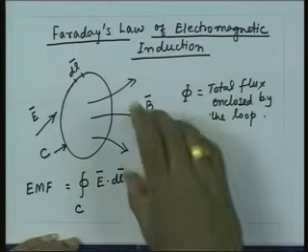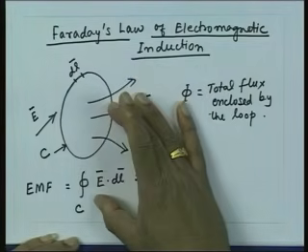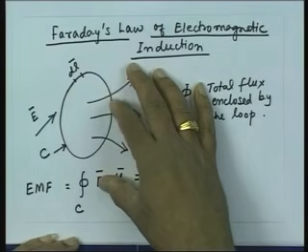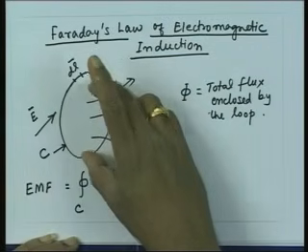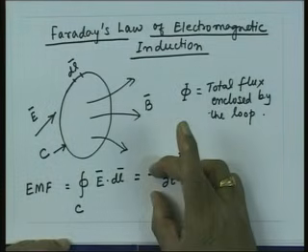What that means is whenever the magnetic field tries to induce the EMF in the loop and the current flows, the magnetic field produced by that current tries to oppose this. So, this phenomenon cannot go on increasing indefinitely. So, the magnetic field produced by the current produced by the EMF essentially tries to provide a resistance to the original magnetic field. That is what essentially this negative sign represents.